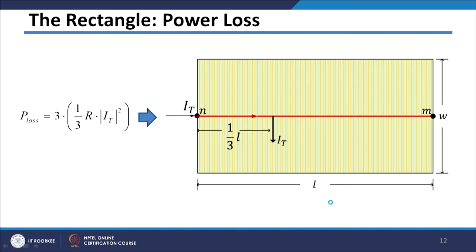By seeing this equation, you can easily find the lumped model for calculation of power loss. It tells me that at 1/3 R you have to put the whole current. So, you can see that at 1/3 length, the resistance till this part will be 1/3 R, and the current will be IT. As I told you, in this case also we can lump this at the end.